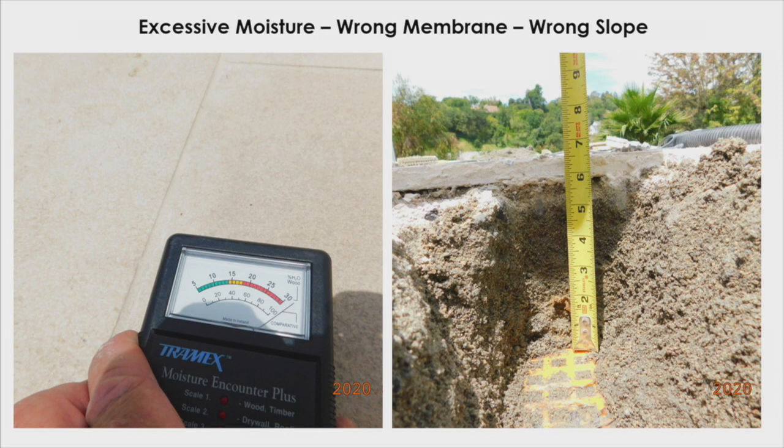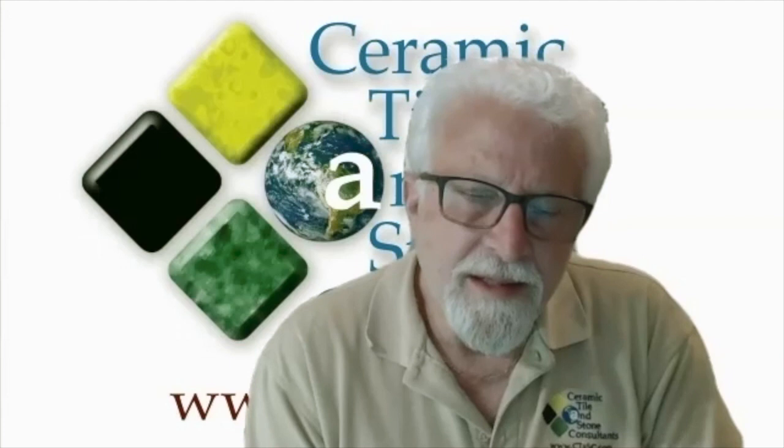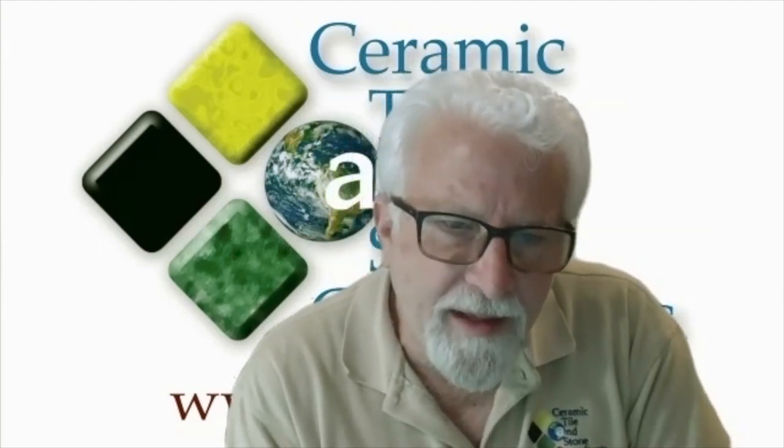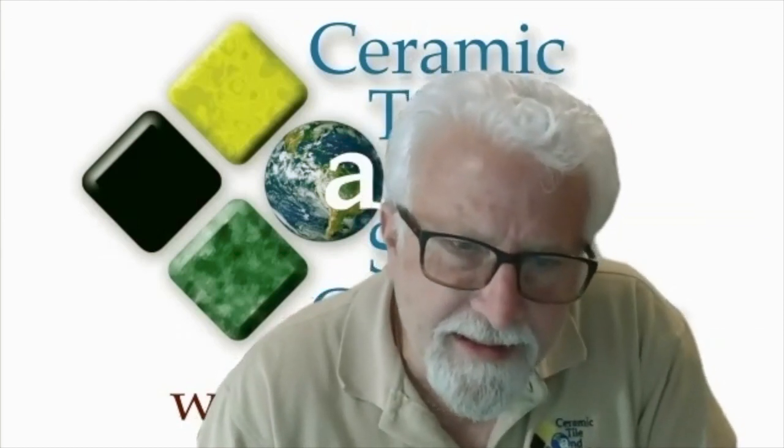It absorbs moisture. The next thing that was wrong is they had this Ditra uncoupling system there. Well, Ditra uncoupling is designed for the tile to bond directly to it, not to be under a mortar bed. Ditra actually has a drain mat, so it would have been more logical if it was a drain mat where it would have a covering over the plastic so water could then drain readily away as long as it had somewhere to drain to, which in this case, it doesn't.